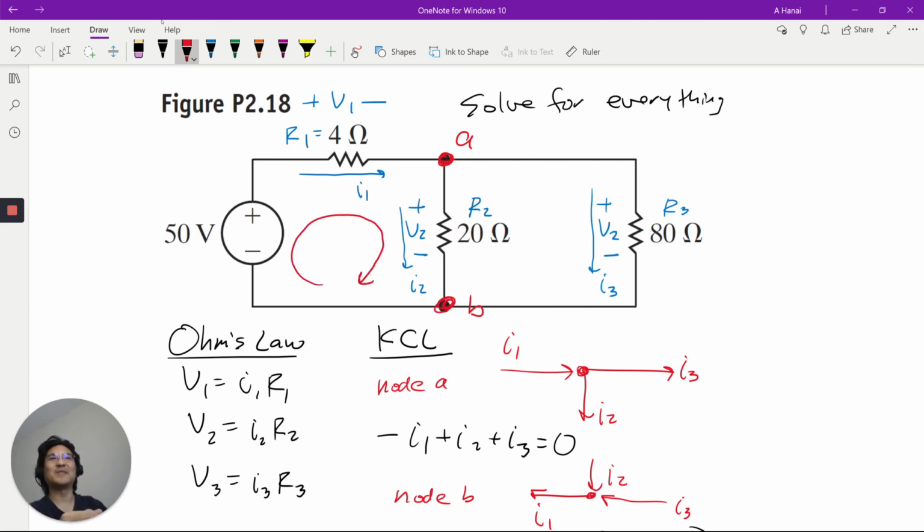So how about we go over here? I'll call this path C. And you can choose clockwise, counterclockwise. Doesn't matter. Okay, so I just happen to choose clockwise. You can choose counterclockwise, totally fine. Okay, so let's go this way. Is that positive or negative? That's voltage rise, right? Because positive is drop. So this is negative 50, right? Negative 50. Going this way.